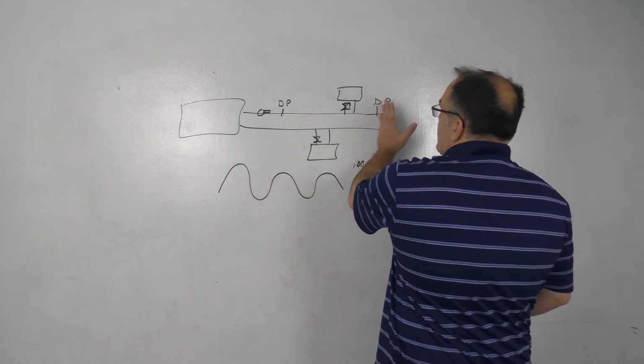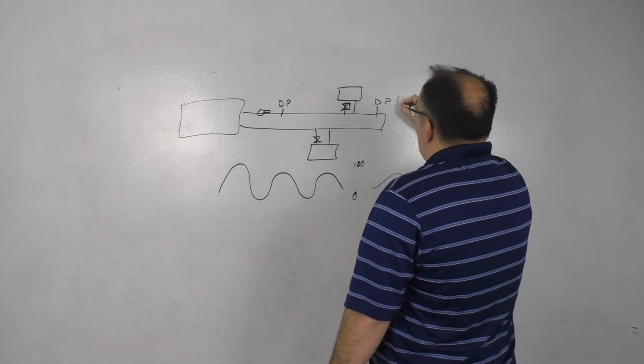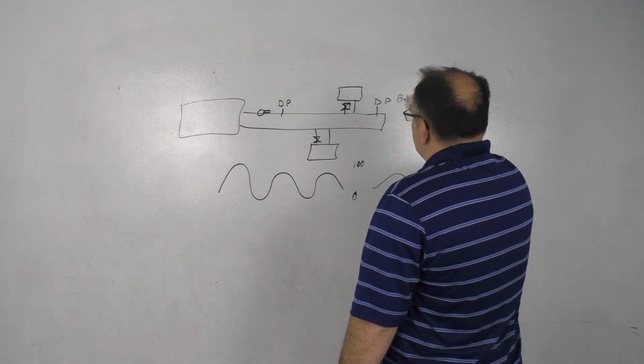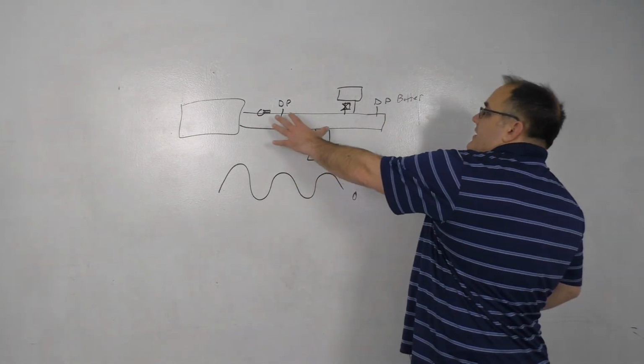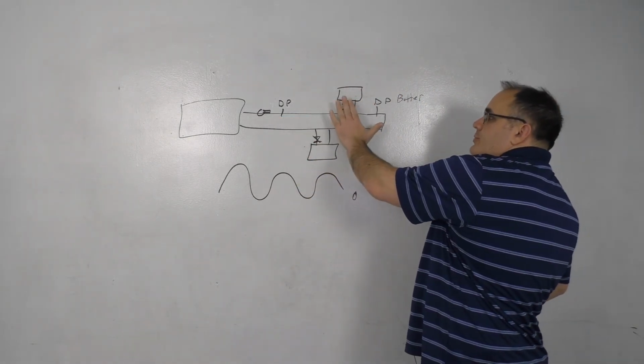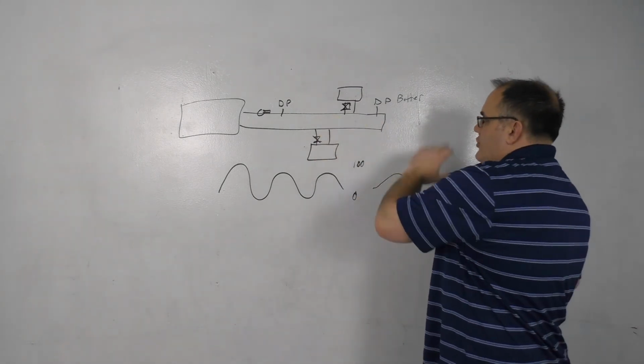And that's why you want to move the differential pressure down here, so that you will have better control, because you're actually giving the pump time to push water to both of these coils. And in a plant, there would actually be a lot more coils.